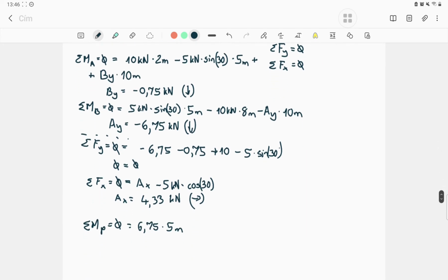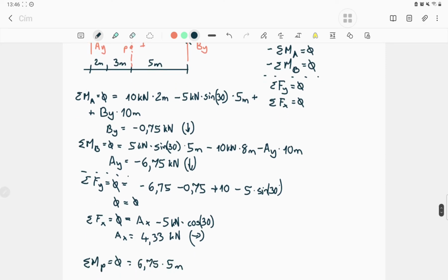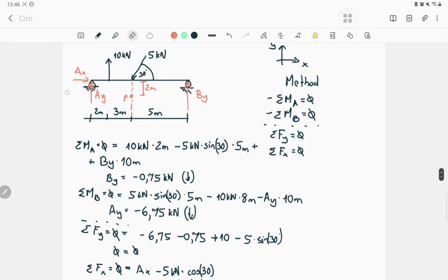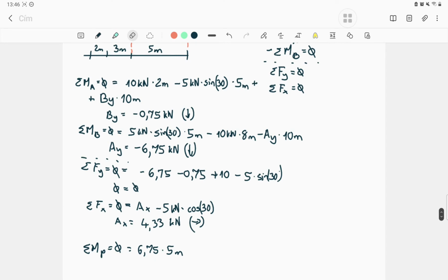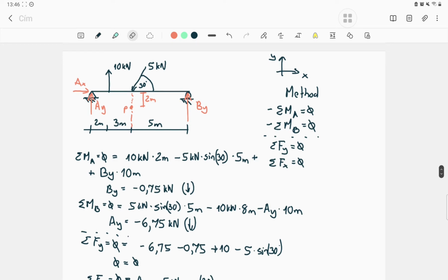Now the direction. As you see, I wrote everything in positive, so positive rotation, but the AY you can see here is going down, while the original went up. It doesn't matter, you can check the original drawing, or you can keep the good results. I suggest every time using the good results, because when you draw, the AY and BY directions may be good, maybe not.